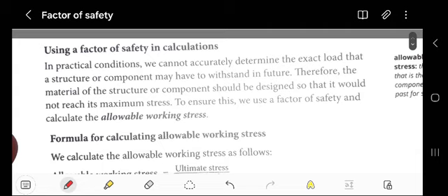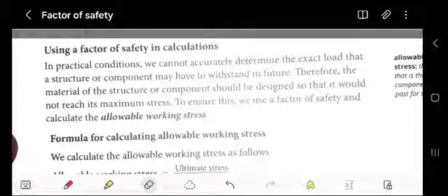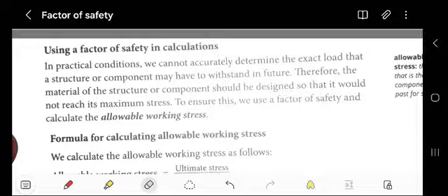Imagine you are designing a car made to carry 4 passengers, then suddenly you decide to overload it with maybe 5 or 6 passengers. Then what about when you are driving over humps and bumps? So in other words, the factor of safety prevents our object from reaching the maximum stress by doubling what the maximum expected stress is, so that will increase the safety as far as possible.